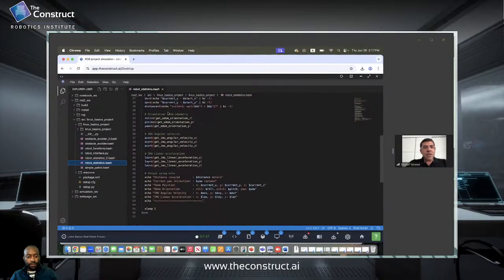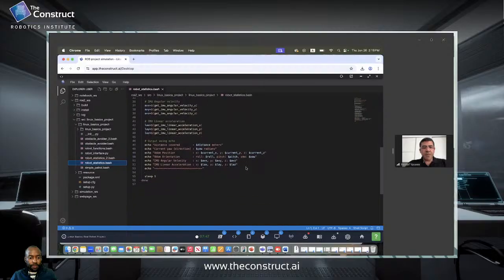In addition to that, we calculated and showed the orientation from odometry as well, represented by the roll, pitch, and yaw. After that, we calculated and showed the angular velocity and the linear acceleration of this robot, which helps the viewer of this program to troubleshoot what is occurring on this robot and what the robot status is at a certain point in time. Okay. All right.